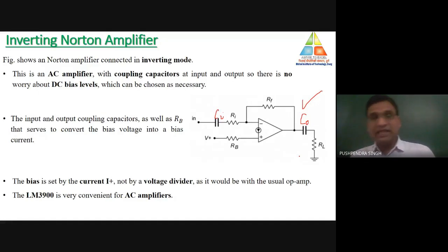I think you will remember that in the case of the IC741, there is direct coupling. The disadvantage of direct coupling is that when all the transistors are connected directly to each other, then AC as well as DC signal will be amplified inside the operational amplifier. So the operating point was changed in the case of IC741. There we needed to use one extra block called the buffer or level shifting block, whose main use was to reduce the amplified DC voltage to 0.